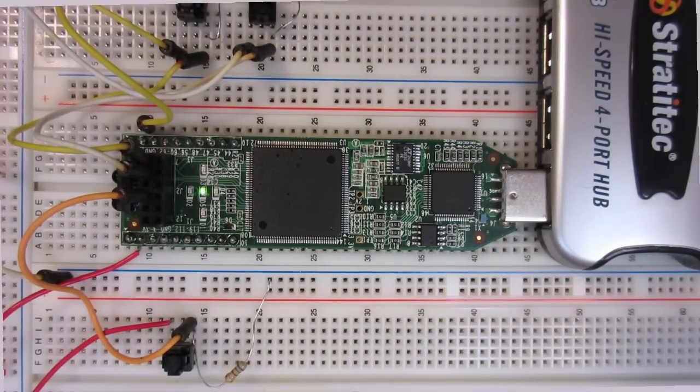The value of the resistor is not very critical, but without them it takes a little while for the floating input pins to discharge after you let go of a switch. Apparently there are no onboard pull-ups or pull-downs on the board. You can see the LEDs are already blinking because of the multi-stage timer we built in Verilog, and that looks to be about half a second.